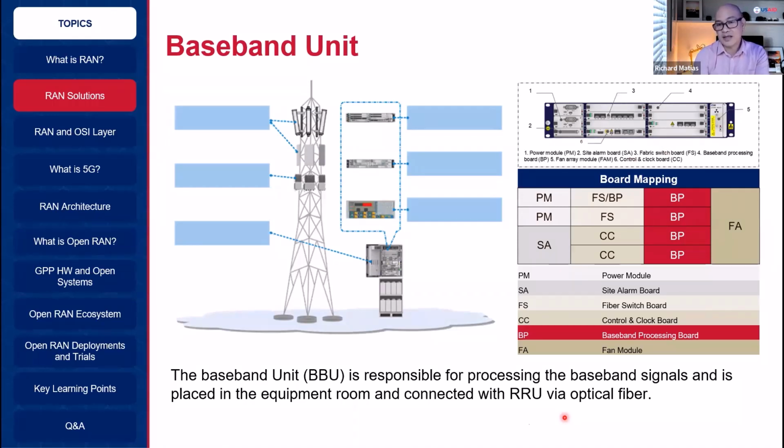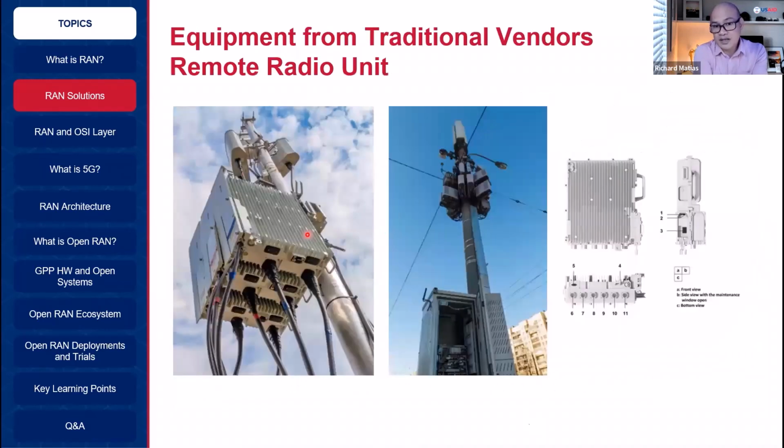Okay? So dito rin sa baseband unit, when you want to activate GSM, UMTS, LTE, or 5G, you can activate it here, if the radio unit is capable of that certain frequency. There are radio units kasi, no, na tinatawag nating SDR, software defined radio, that are not very technology specific, only frequency.